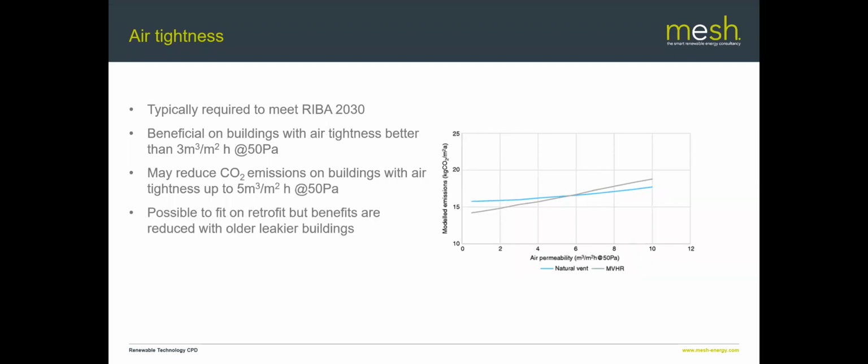It's obviously possible to retrofit MVHR, but as I said, you get a reduced benefit on older, leakier buildings, so you might be better off concentrating on other areas of improving the building efficiency, such as increasing the air tightness, or just increasing the insulation.